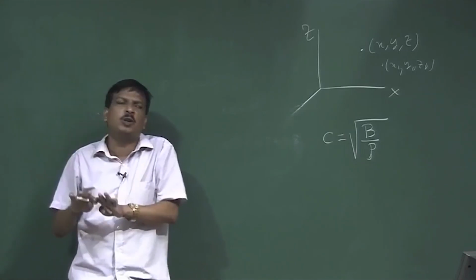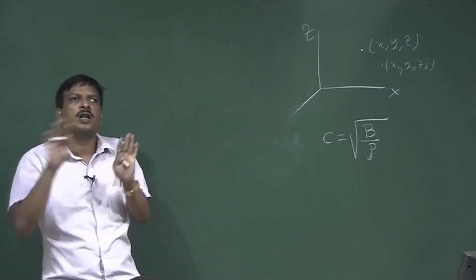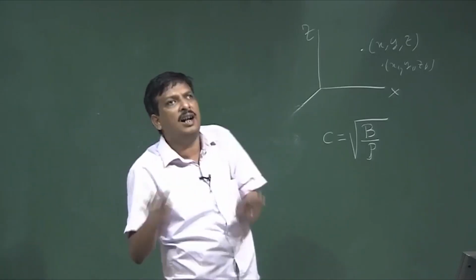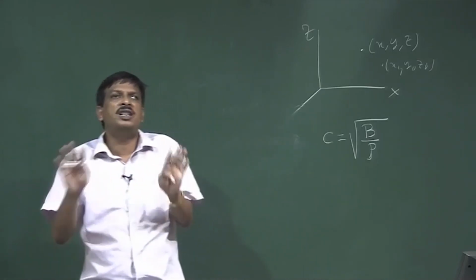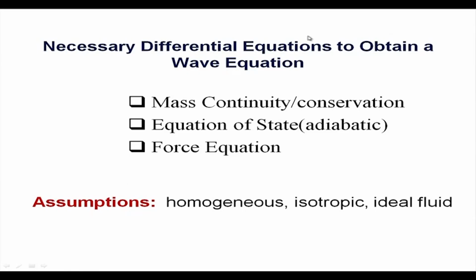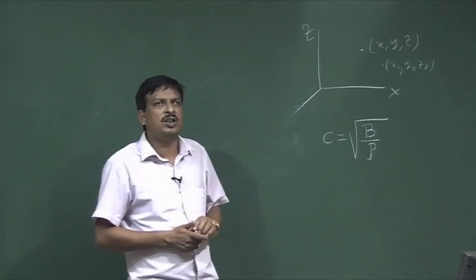So, for a linear wave equation, we consider the medium is homogeneous, the process of sound transmission is adiabatic, there is no heat loss, and the fluid is ideal, that means there is no friction, no viscosity. Okay. Then we employ these 3 simple principles. One is called continuity of mass or conservation of mass, then another is called equation of state, and another is called force equation. So, those 3 equations will be employed during the derivation of that pressure wave equation.